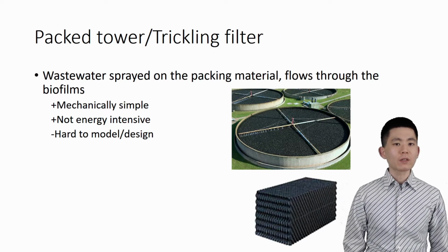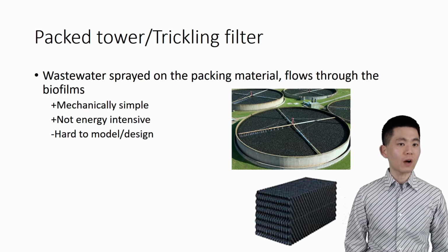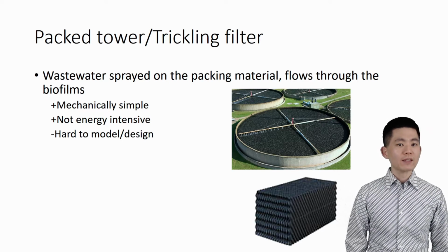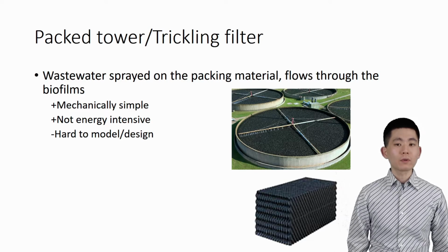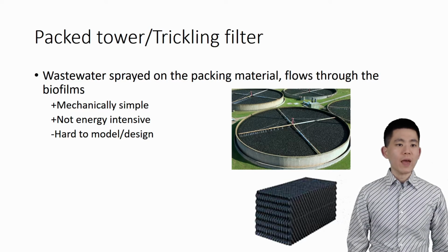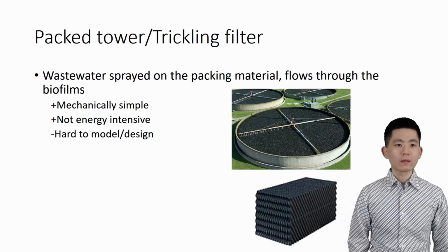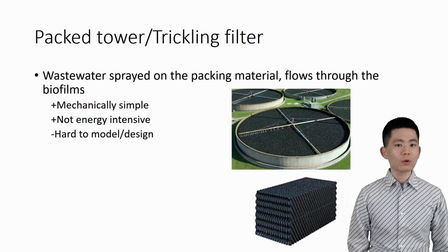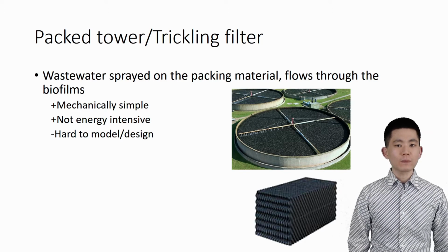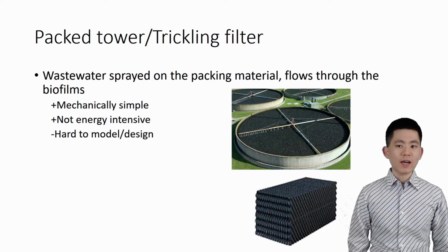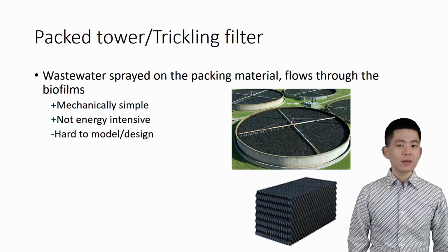Attached growth reactors may have configurations that are different from the conventional CSTR, PFR, and batch reactors. Packed tower is an example. Wastewater is sprayed on the packing material and is degraded as it trickles down the biofilm grown on the packing material. Even though it is mechanically simple and very energy efficient, it is very hard to design and model, as the hydraulic condition and the formation of biomass in the packing material are very difficult to determine.